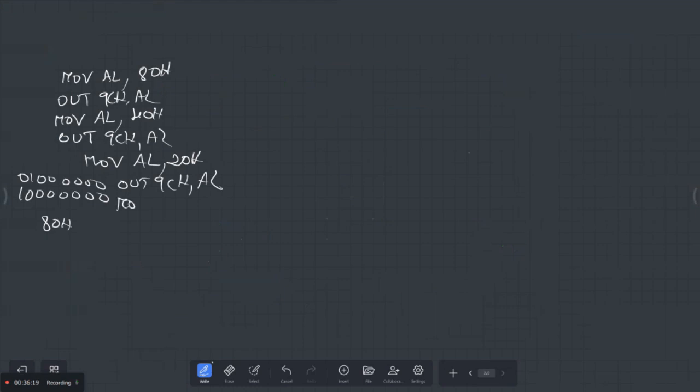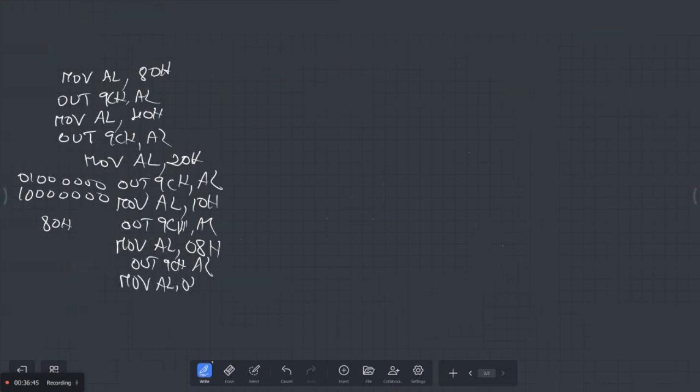Tell me. Move AL, comma 10H. Okay, out 9CH, comma AL. Next, move AL, comma 08H, out 9CH, AL. Next, move AL, comma out 9CH, comma AL.